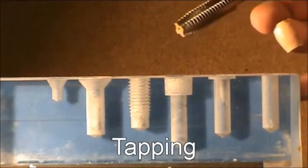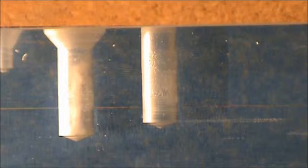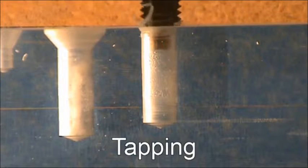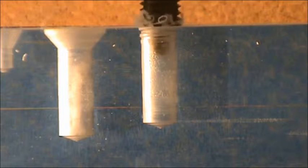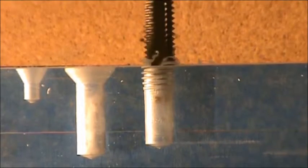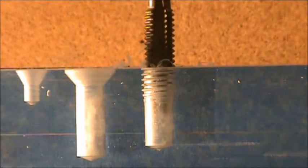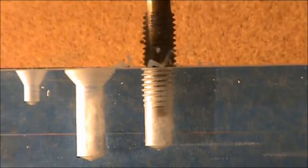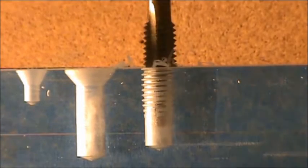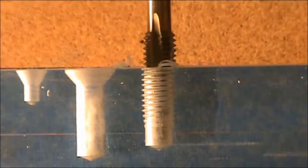The second one is tapping. This is the tap. Its function is to put a thread inside a hole. First we chamfer the hole a little bit to make it easy to enter, and then we put the tap in a little slowly so it won't incline in one direction. As we can see, we move the tap back and forth to enable the chips to get out easily. And then we can continue the thread until the end.